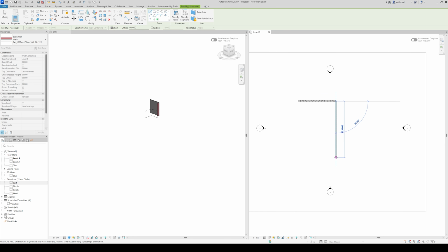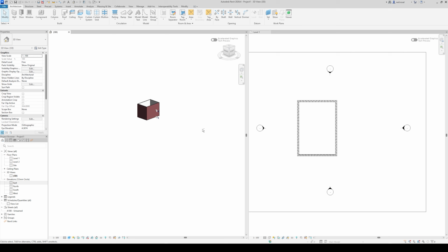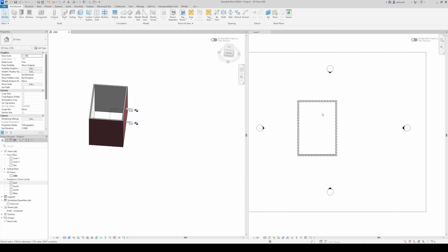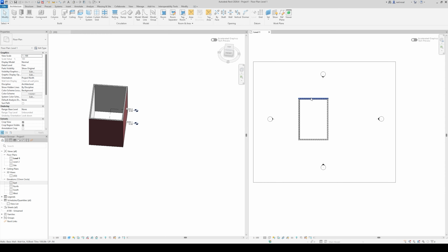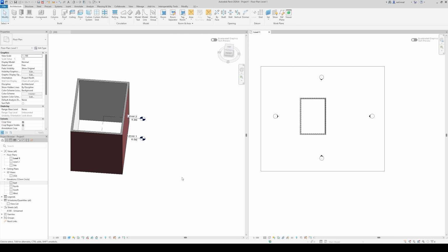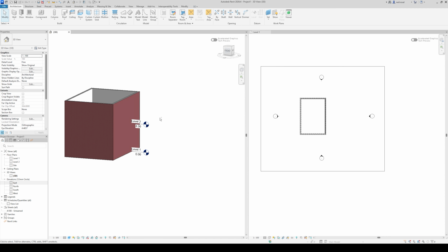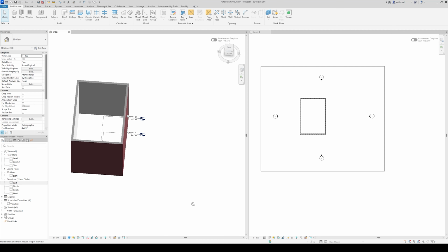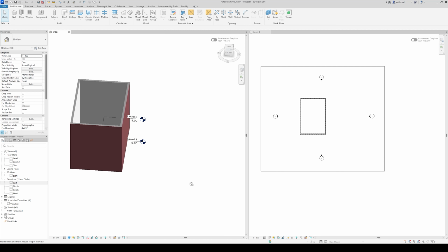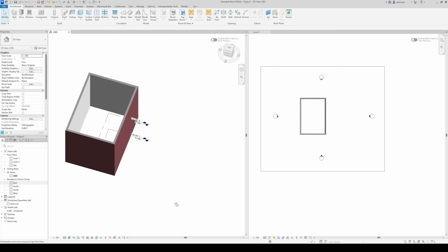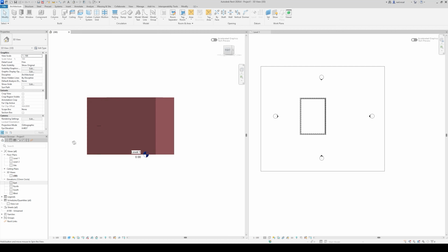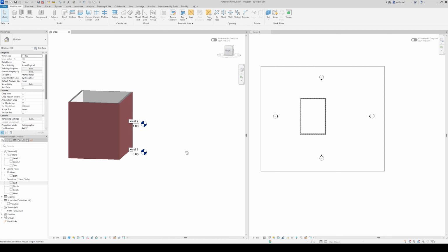What I like about Revit is that it snaps really great. There's a lot of guidelines to it, so you won't get lost. So we have our 7 meters by 10 meters box at the current moment. And as you can see, whatever happens in plan view happens in 3D view. That happens between all views, whether you model or draw, which is an efficient way to do your studio projects nicely. So that's really a nice thing.